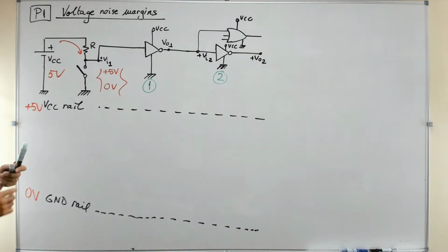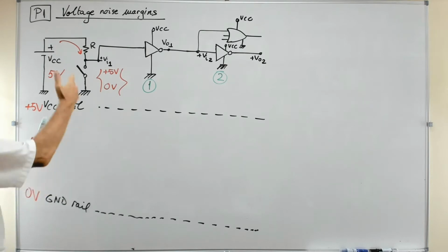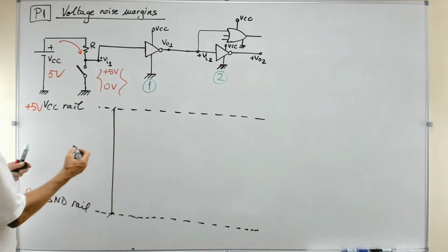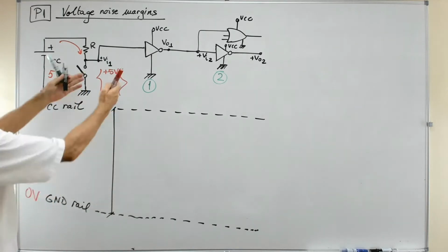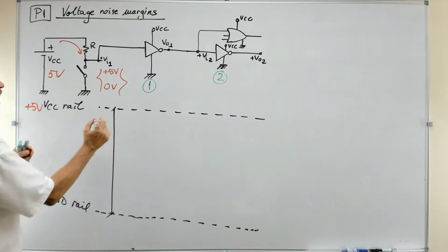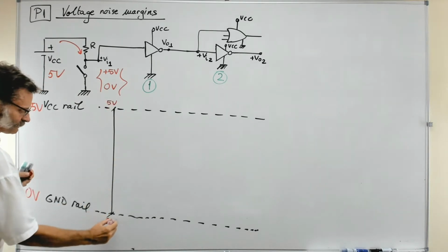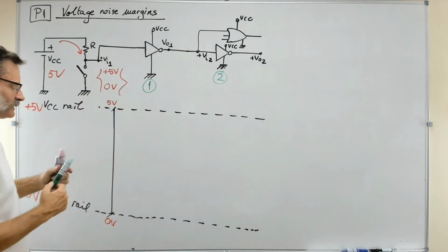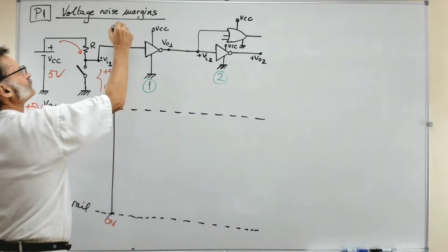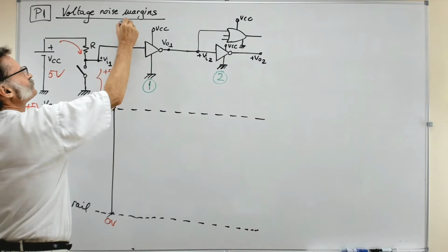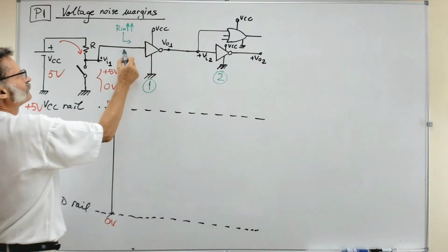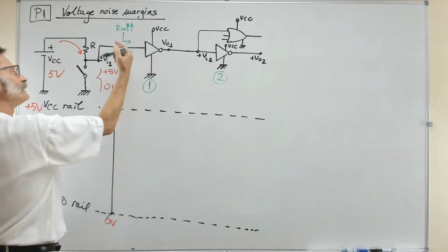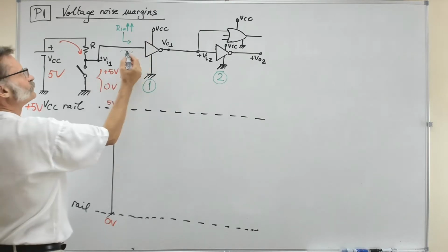Okay, so now if you think about voltages in this way, imagine a vertical axis or line like this. You may say that here, yes, it's like that. 5 volts when you are not clicking and 0 volts when you are clicking. That is clear because there is nothing else. Imagine as well that this gate has an equivalent circuit that has an input impedance which is extremely high. So don't worry about the current that may go inside the gate, or maybe sourcing from this input is 0.